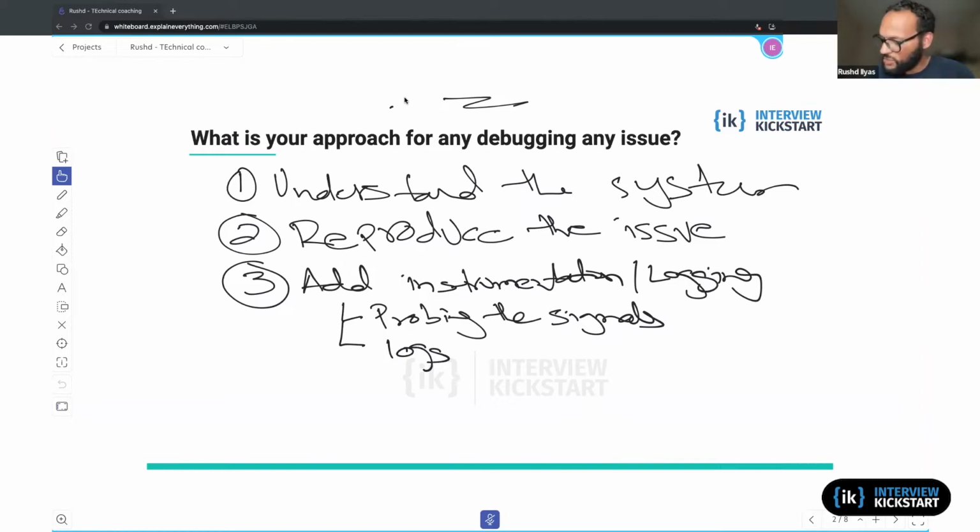The third thing is, if you're running an RTOS or something like that, again, it falls under the logs, but enabling the crash logs helps a lot. If you know that the system is crashing, in that scenario, what was the state of the tasks? So basically just enabling a debug build usually also helps. So these all fall under instrumentation or logging, which are usually disabled in the customer application.